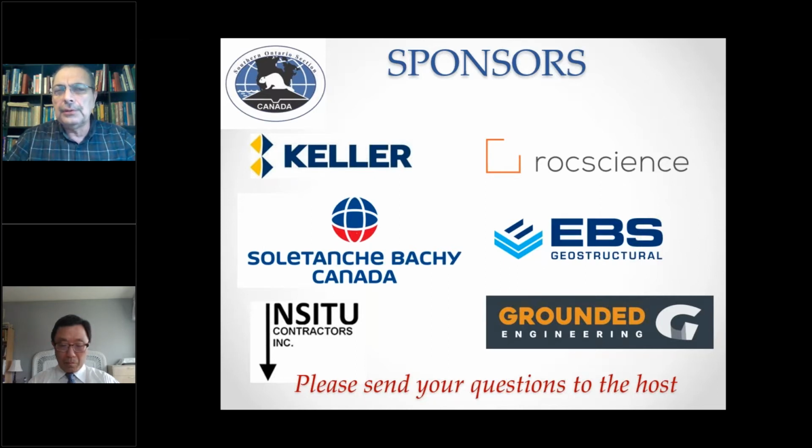All the mixers coming to the site have very controlled temperature, and the temperature is taken many times before you start pouring. This is very important. Also, we have retarders used in concrete so that you can control the setting time and the hardening, the shrinkage effects on the hardening. Yep. Okay. Thank you.